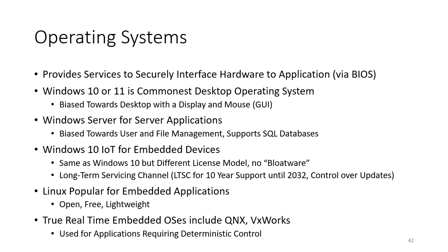For real-time control, Linux is sort of real-time, but not quite. Windows 10 has real-time extensions, but it's not really real-time. So if you want the true real-time embedded operating system, you could use something like QNX or VxWorks. And those are for applications that require very strict deterministic control with very good support in the operating system and the application level to stop applications running away.